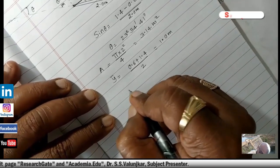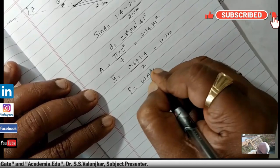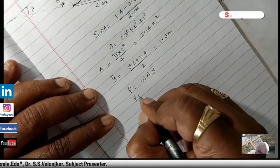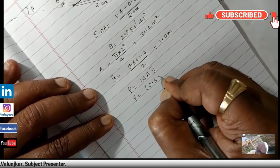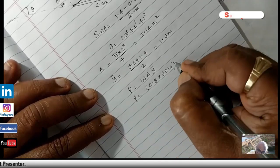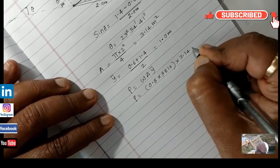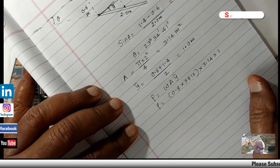So P is equal to W A Y bar, which is 0.8 into 9810, the specific weight of water, into 3.14 into 1.